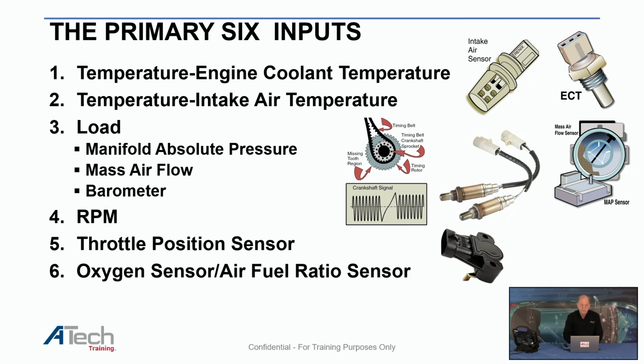So the first 2 up there are for temperature. We have to know the coolant temperature and the intake air temp sensor. That makes a really good combination. On a key on, engine off car that's been sitting overnight, they should be within 10 degrees of each other, and that gives you an idea that you're off to a good start. The coolant temp sensor has more influence than the inlet air temp sensor, but you have to have both to do a good job of understanding.